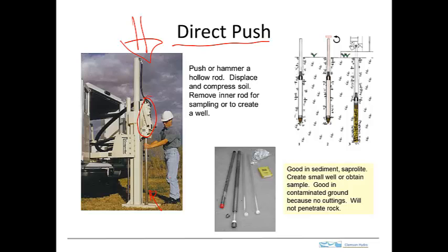And so these direct push techniques are used in the environmental industry extensively because it's a way of getting samples of the potentially contaminated sediments or water, and it's relatively quick and relatively inexpensive. So if you have a contaminated site, you really want to understand the distribution of the contaminants, and that means making lots of samples. And so you've got to keep the cost down.